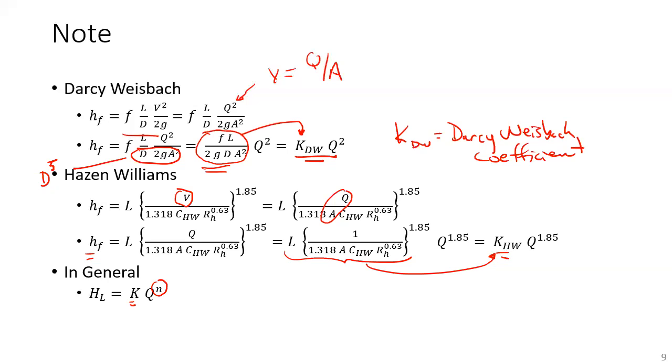The practical application, though, is that in the field, what we may have is a pipe underground. And we may not know how many valves are in it, if there are any valves. Also, that pipe could have been put in the 1800s, so we don't know if there are big holes and leaks in it. We don't know the status of the corrosion until we dig it up. But we don't want to dig it up. We just want to understand the friction loss characteristics of the pipe.